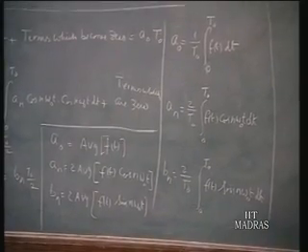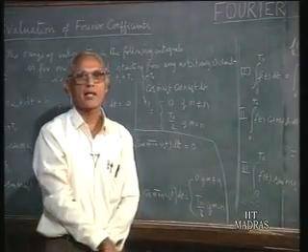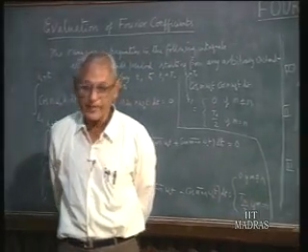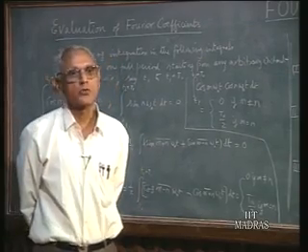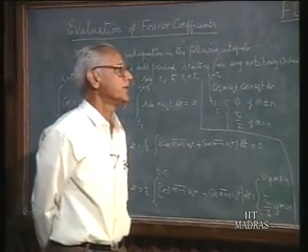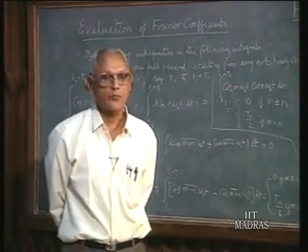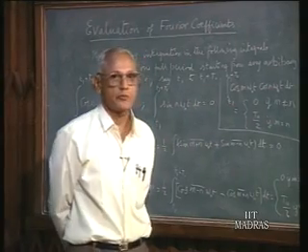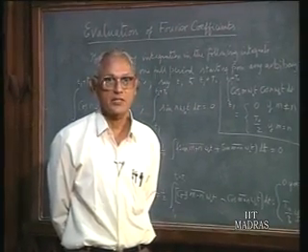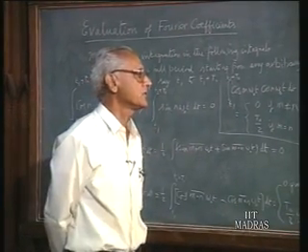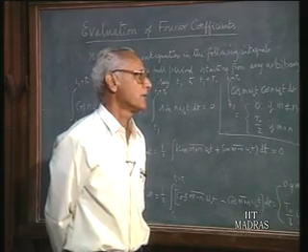Now, as far as the integration is concerned, if you have got analytical expressions for f of t, you can carry them out analytically, or you can also do them numerically if f of t is given, for example, in a graphical form, a waveform is recorded, and you would like to perform the Fourier series analysis of that, then you can carry out these integrations by numerical methods.